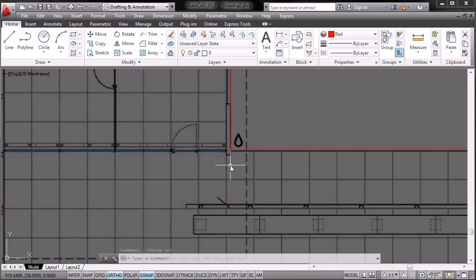And now if we ask for the polyline tool, PL, enter, as soon as we are close to this area where we have this corner, it will show us this small green rectangle. And this green rectangle is actually our endpoint snap, and it will appear whenever we're close to a vertex of an object. And if we make a click, it will snap the starting point of the line to it.